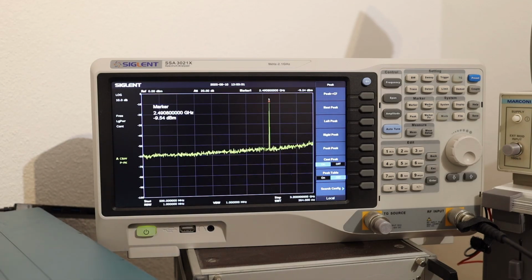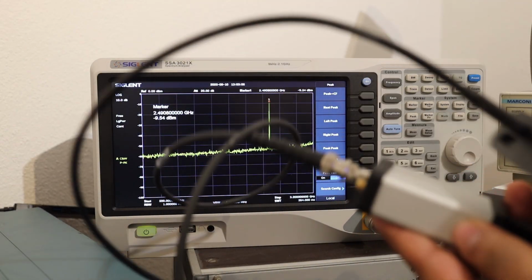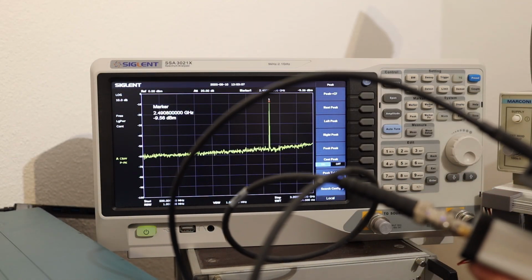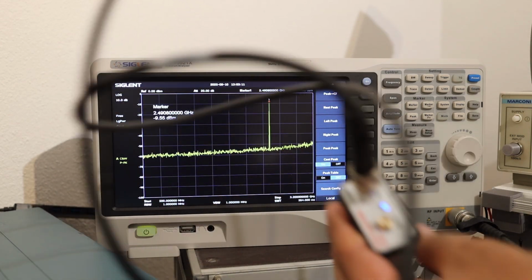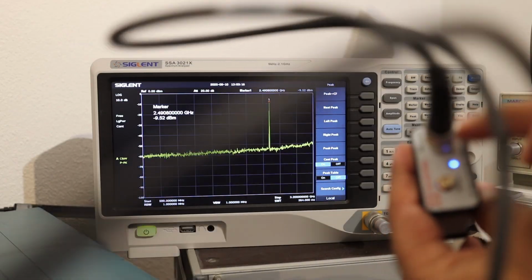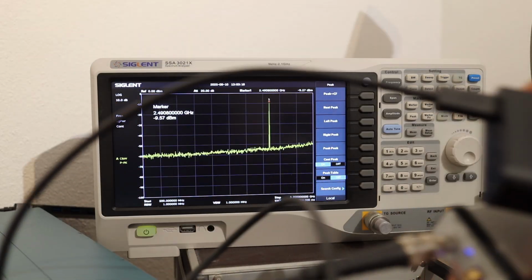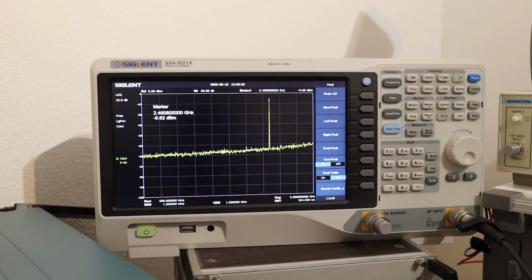So right now the device is connected to a power bank, something like this, and it's not connected to a computer, and you see the frequency which we programmed, 2.5 gigahertz, is available at the output, of course, and you see the output PLL locked LED as well. This gets locked only when the PLL is locked and output is available on the device output. So this standalone operation allows you to do whatever you want without the need of a computer.